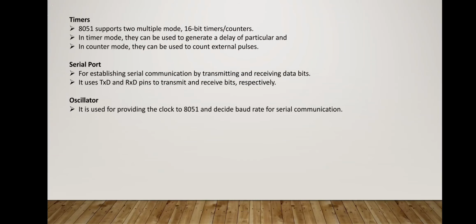Then we have timers. The 8051 supports two multiple-mode 16-bit timers or counters. These can work as 16-bit timers or as counters too. In timer mode, they are used to generate a delay, and in counter mode they are used to count the external pulses.